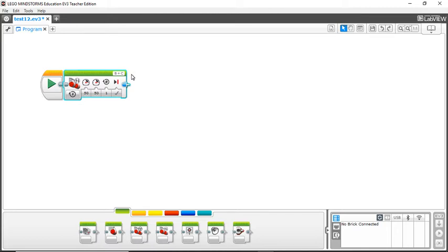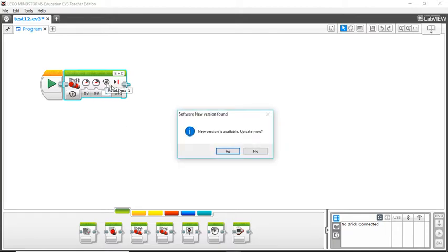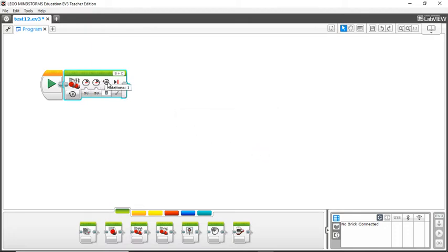So now that you have your motor selected, the first box right here is kind of like the units you want to measure in. Typically you measure in rotations. So now that you've selected rotations, you have to type in how many rotations you want your motors to drive or your wheels to spin. This box right here is where you type in your rotations, and you can type in up to 2 decimal places. So you can even do 3.16 rotations if you want to.